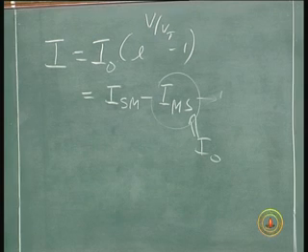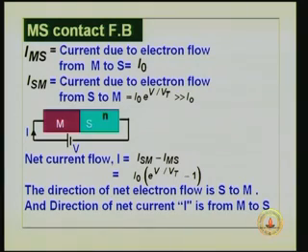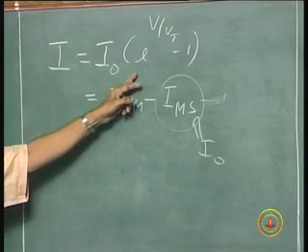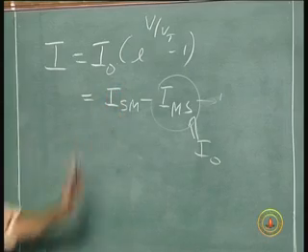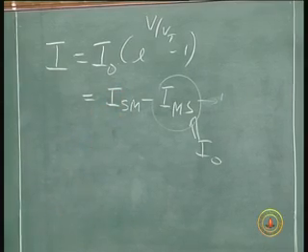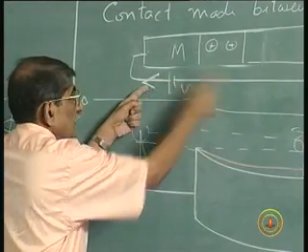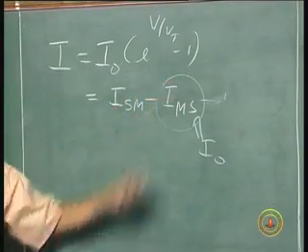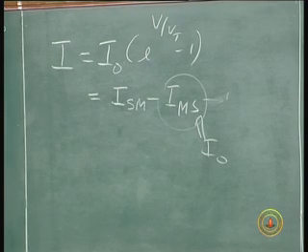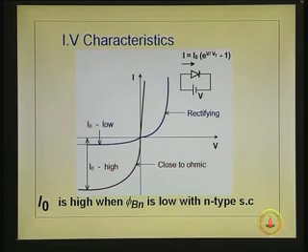Okay. So, the point that I was trying to point out is ultimately you can use the same equation. If you drop this down to 0, how do you drop this down to 0? By making V minus V r, reverse bias. So, that becomes minus I naught, telling you that if I reverse this polarity, whatever current was there will be in the opposite direction with only the second term, metal to semiconductor. Okay. So, these are some of the aspects which make it clearer, and now again I am re-showing once more